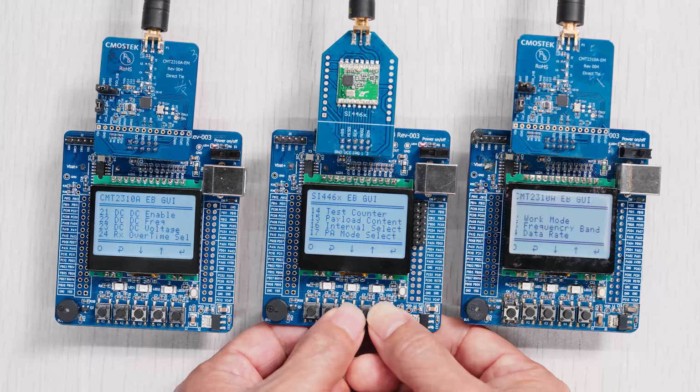Press the FM key on the front panel and set FM to on. Set FM DEV to 25 kHz and set FM source to external AC. Press the Mode key and set BERT to on.